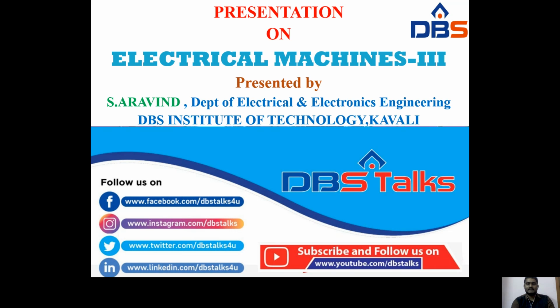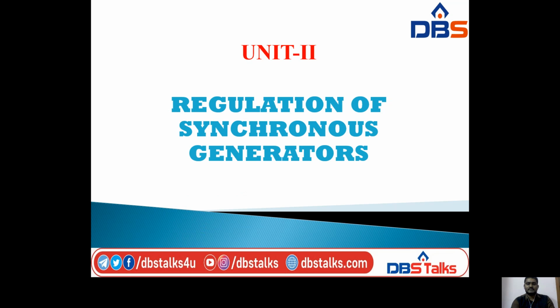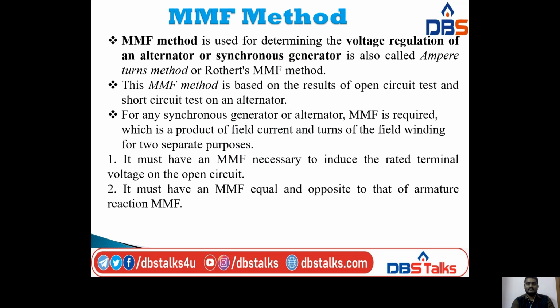Firstly, we will see the diagrammatic representation of the MMF method. The MMF method is used for determining the voltage regulation of an alternator or synchronous generator. It is also called the ampere turns method, or Rother's MMF method, as I discussed in the first class. This method is based on the results of the open circuit test and short circuit test of an alternator.